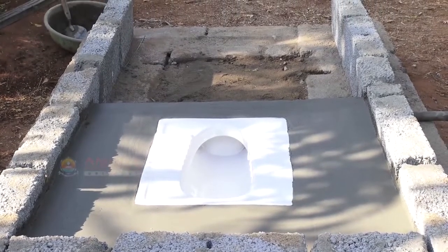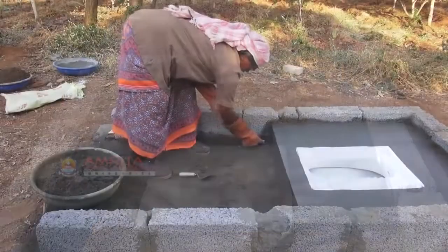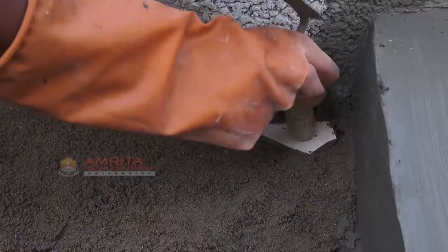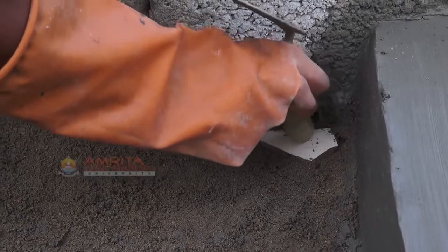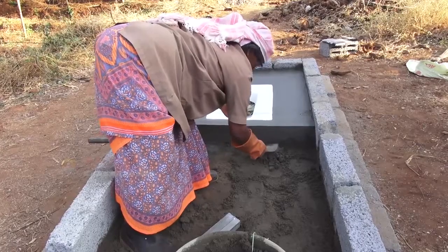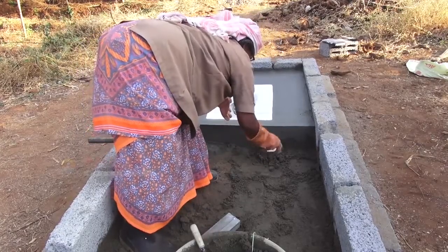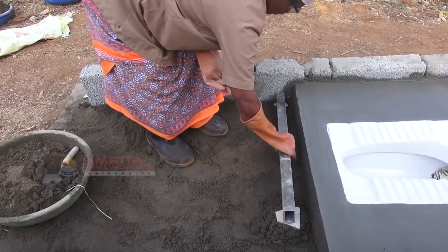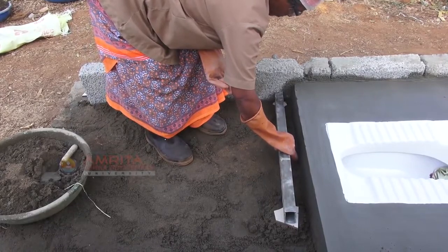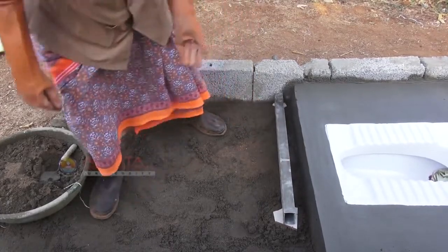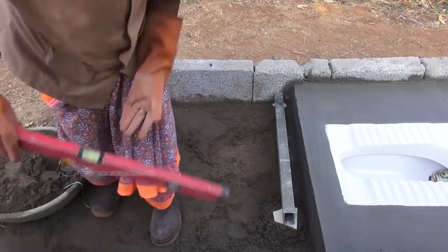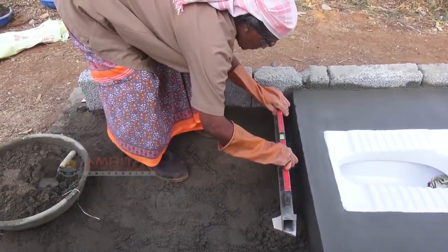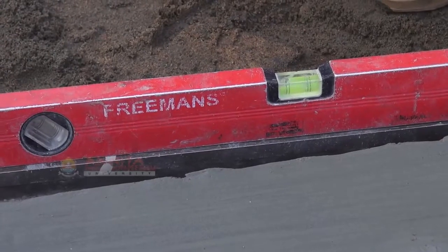We will now proceed to slope the bathing area. Place a tile beneath the drainage pipe. Keeping this tile as reference, place tiles at other corners of the bathing area at an elevated height. Check the elevation by placing one end of the straight edge on top of the tile beneath the drainage pipe and the other end on top of the tile placed at an elevated level. Place the spirit level on top of the straight edge. The bubble tends towards the higher level.